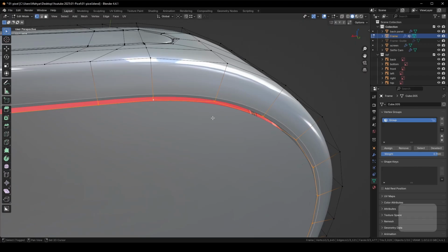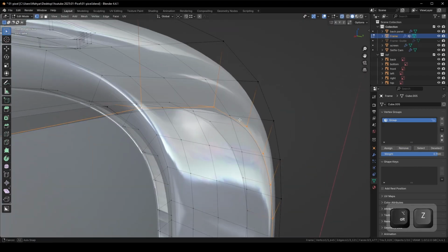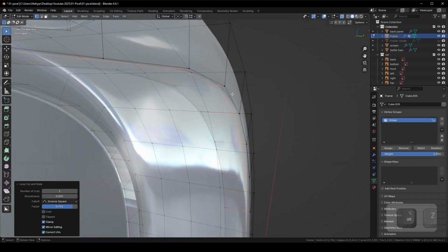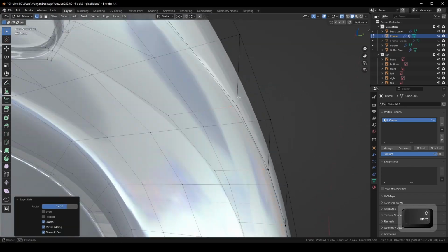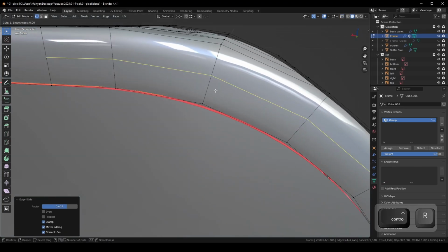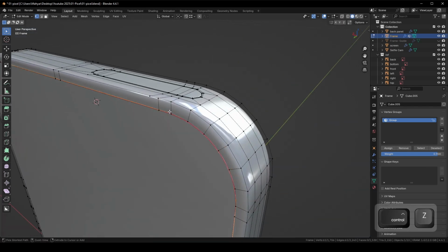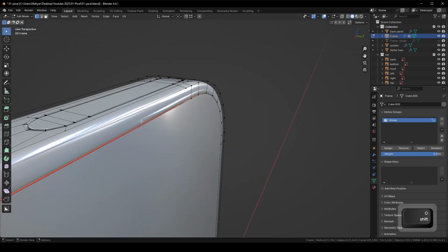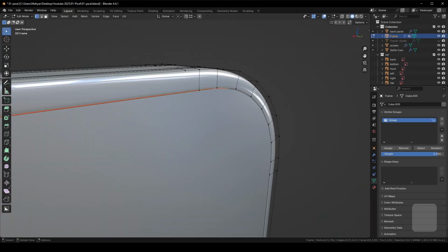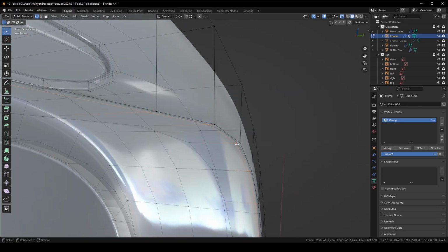Not the result I need. I totally remove this and add a control loop because we don't need any shrink wrap here. I think we need more sharper edges in the back panel. I can add another edge loop here to make it more sharp. Since we have n-gons here, we can't create edge loops here, so I have to manipulate here by just this edge loop.